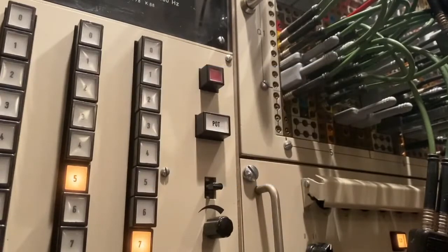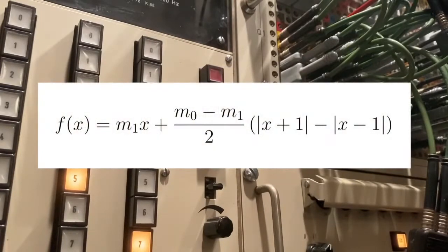The central part of the Chua oscillator or Chua attractor is this strange function f, which you can see here. It's labeled with 4 in the application note. And you see f contains two absolute value functions, the absolute value of x plus 1 and the absolute value of x minus 1. And this f is fed with the variable x and is the right-hand part of the differential equation describing the change of x with time. So this describes the mathematical structure of a Chua attractor.